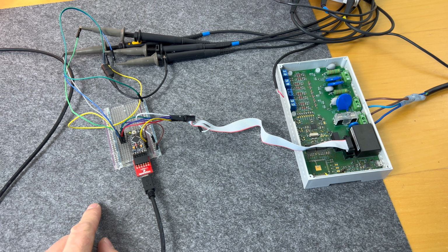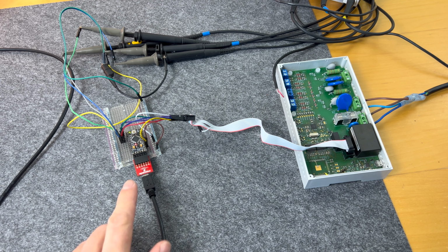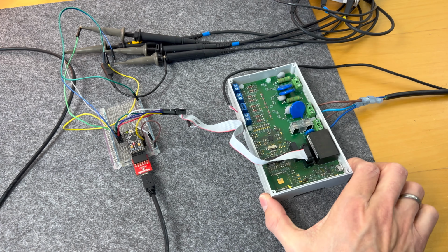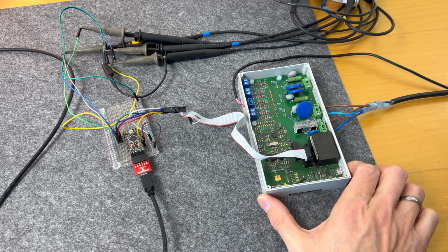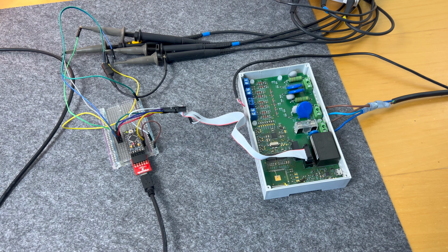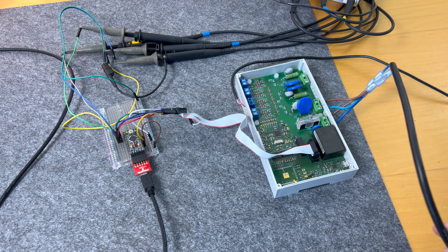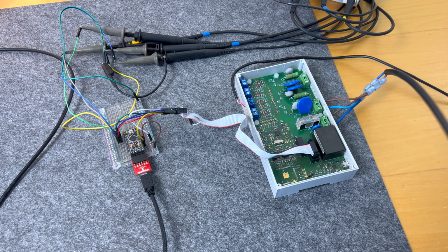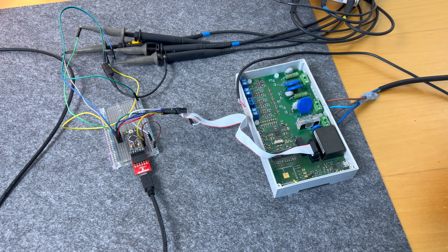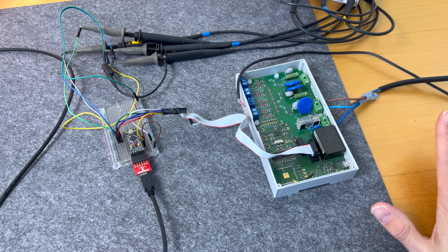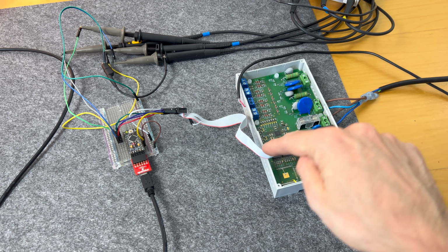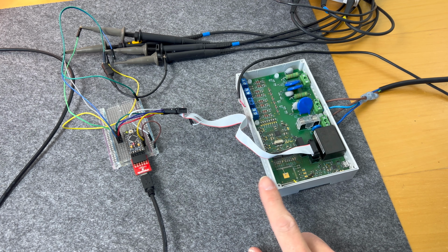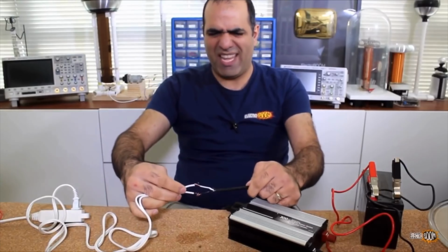The Atmega on this Arduino board here is connected and powered by a computer via USB. In contrast, this energy monitoring IC is directly connected and also powered by a 230 volt mains connection. That's the thick wire going out here. Because of this mains connection, proper galvanic isolation is required so that we can never get in touch with this 230 volts on the microcontroller side here. Otherwise, we might go full ElectroBOOM if we touch it. 120 volt AC.